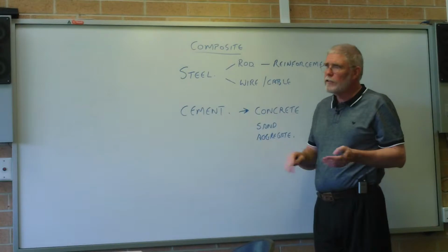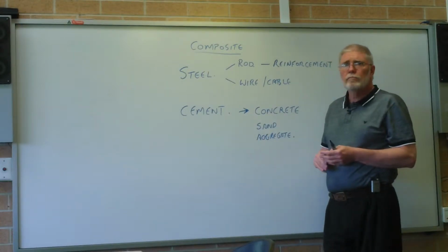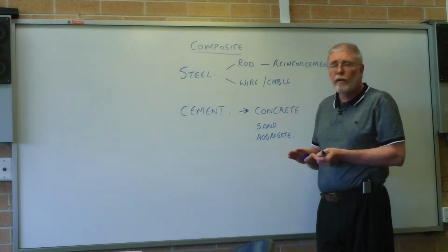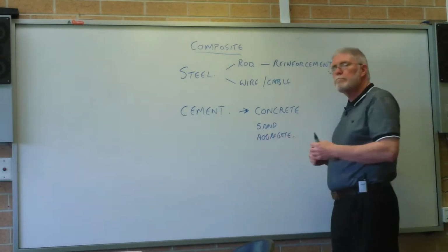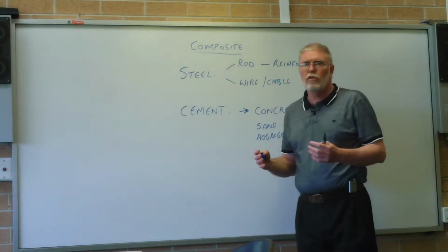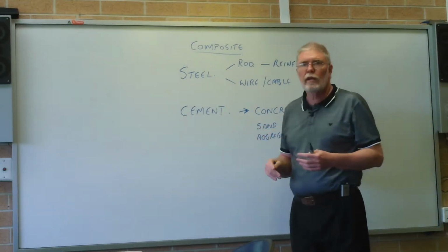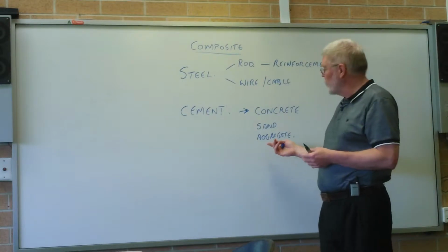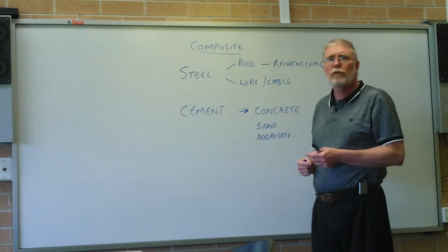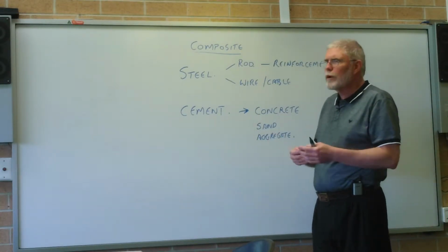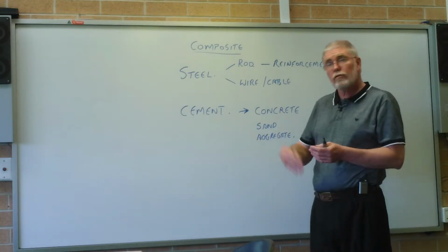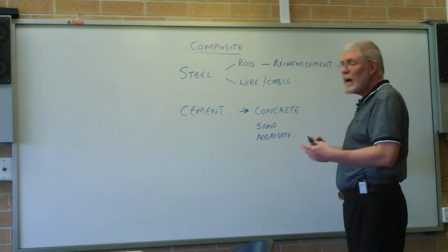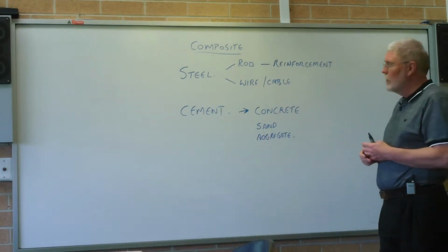A lot of paving is just done that way because it doesn't need the aggregate because the strength requirements are not that high. But aggregate can help bulk it out. So you're not using as much of the cement and the sand, you bulk it out with the materials. You can often throw in old broken pots and things as well. So a lot of concreters will break up old rocks. Old concrete even gets thrown in as the aggregate for new concrete. It's a good way of maintaining and reusing and recycling.